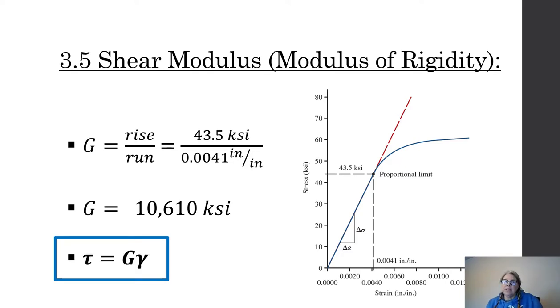The units are going to be our units of stress, which are KSI or a Pascal, because when we look at strain, it's unitless. The normal strain was inch per inch. Our shear strain is in radians, okay? So we have units of stress, KSI, PSI, megapascal, gigapascal, Pascal times 10 to the 6th. Okay, you have to pay attention when you're looking in books to see how the value is given to you. Okay, so we now have shear stress equals G times shear strain.